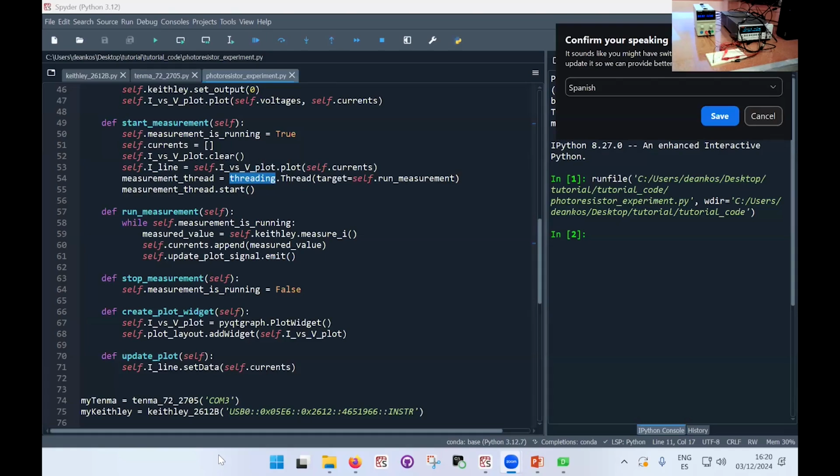In that case, if there's another Keithley connected properly and listening, it will notice that this signal has gone high or low, and it will trigger another effect in that Keithley itself. So I'd say, yeah, with the Keithley, it's a bit clunky, this whole thing. You have to program it. But for example, let's imagine you have a function generator and an oscilloscope, and you need to trigger the oscilloscope to start collecting data when a certain condition is satisfied. Well, ignore the function generator. Imagine you have an oscilloscope and you need to trigger a measurement to start at a certain moment.